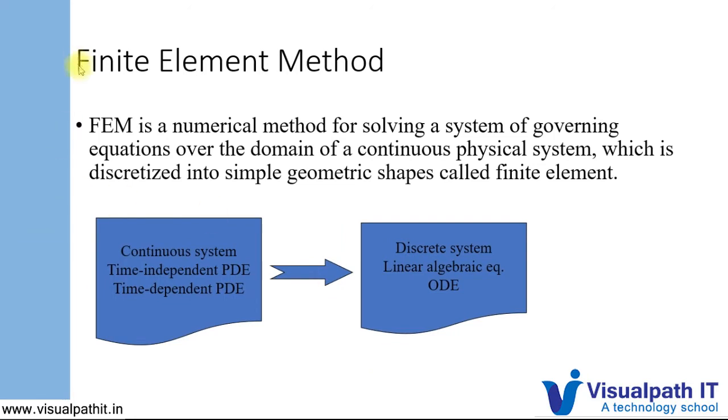So we will be discussing the finite element method in this course in detail. Why are we discussing the finite element method? Because mostly the structural problems, where I'll be conducting more tutorials on Ansys, will be using the finite element method to solve the problems. So as we said, FEM is a numerical method for solving a system of governing equations over the domain of a continuous physical system, which is discretized into simple geometric shapes called finite elements. So what this says is, this is a method for solving a system of governing equations, and these governing equations are formulated over a domain of continuous physical system.